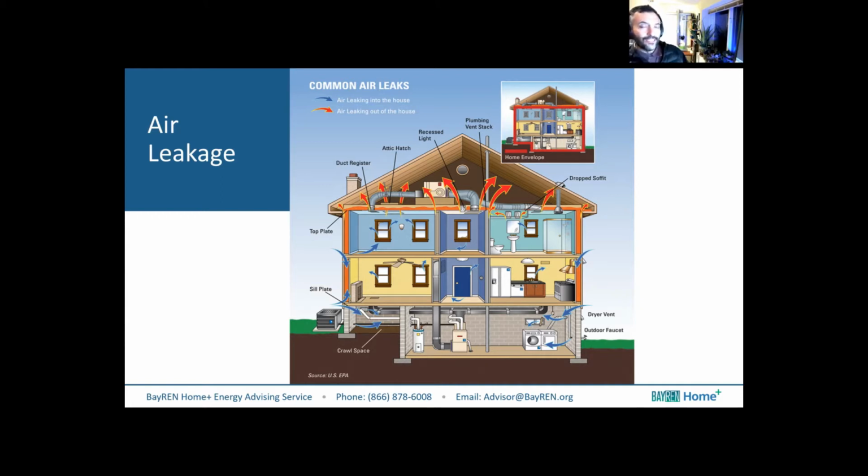So ideally, you air seal that whole plane and you make sure that the roof can vent. It's shading, it's cooling, it gets down to 50 at nighttime. You don't care because the ductwork is insulated, you're insulated, and you're air sealed, and you're totally separated. Windows and doors, it shows it coming in and out here and there, and it's replenishing in through that crawl space.